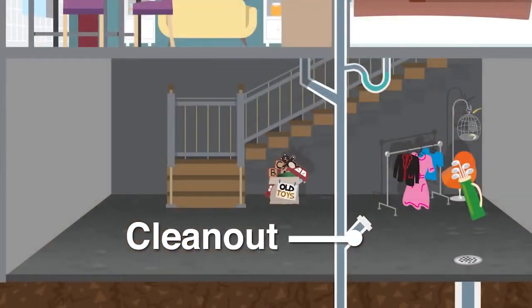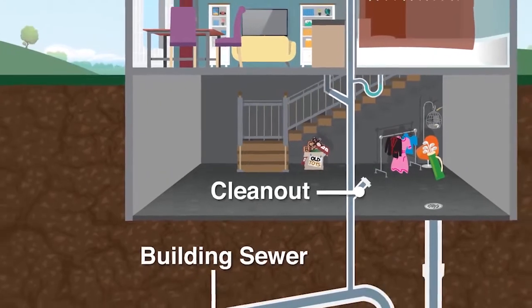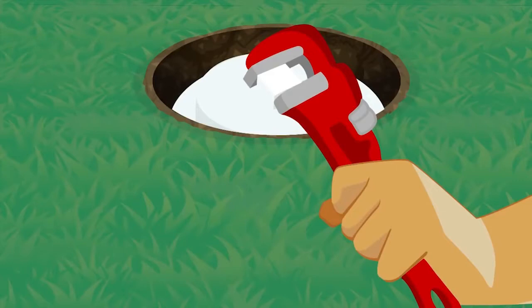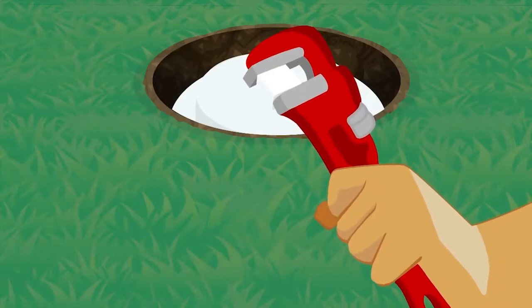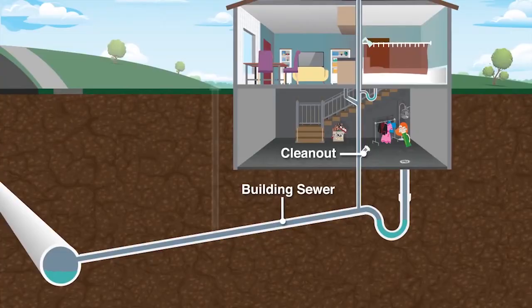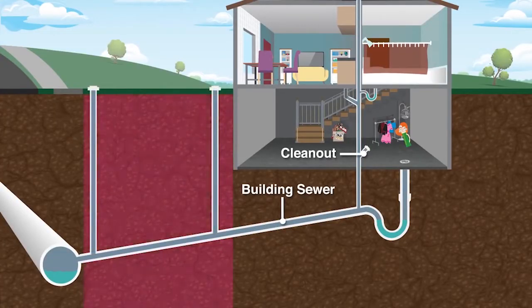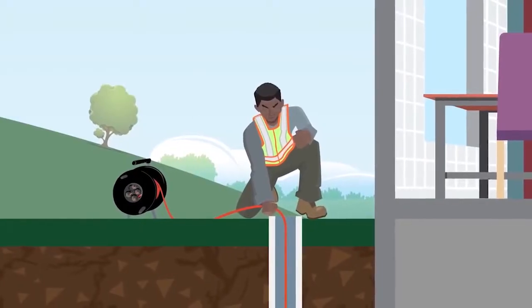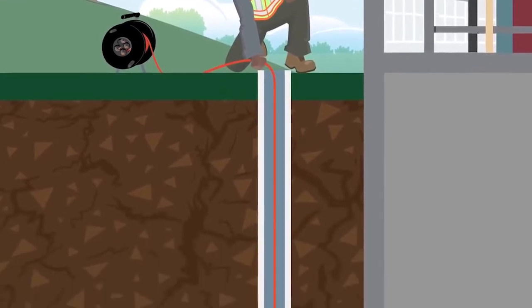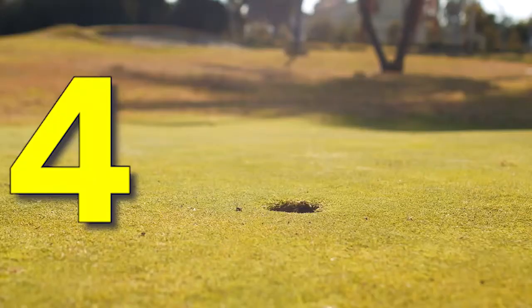Cleanout is a receptacle of the plumbing system accessible on floor, walls, or ceiling. It is equipped with a plug or flush plate so designed as not to impair the aesthetic view of the room. The waste pipe installation must be provided with an ample number of cleanouts strategically located to be opened in case of pipeline trouble.